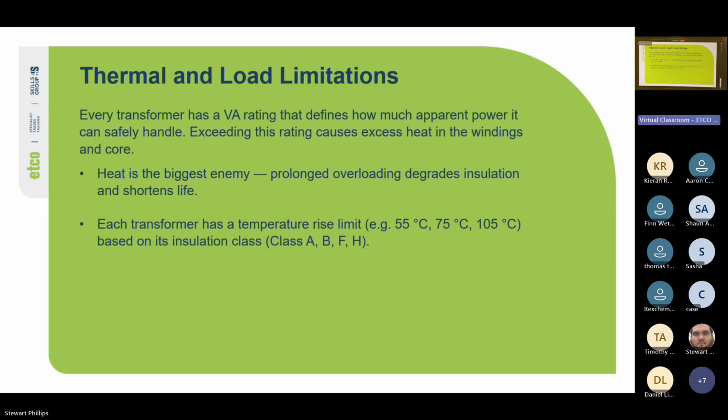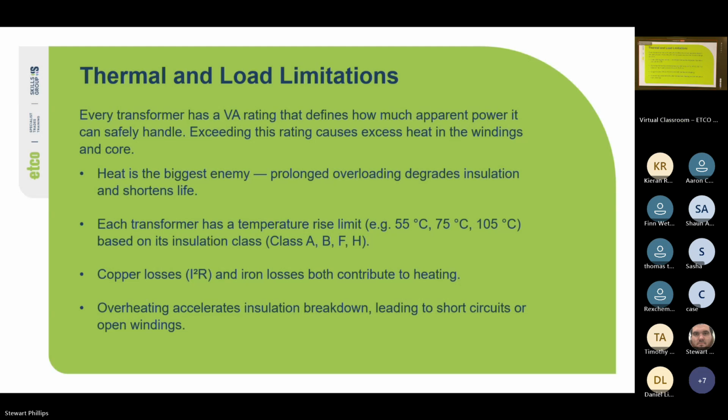Okay, cool. So copper loss, or I squared R, and iron losses can both contribute to heating. Overheating accelerates insulation breakdown, leading to short circuits or open windings.